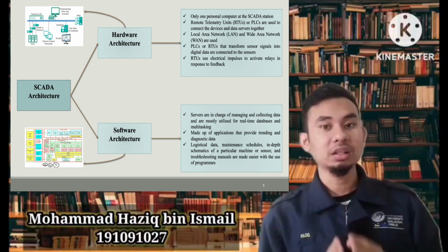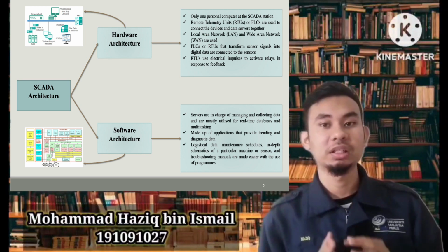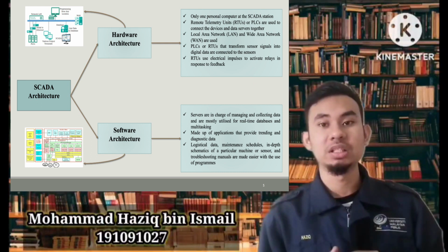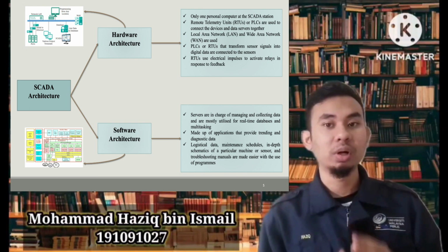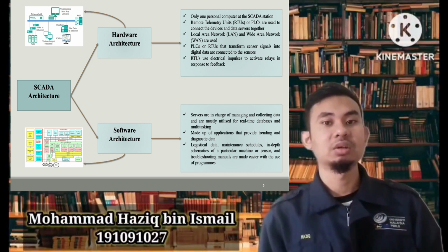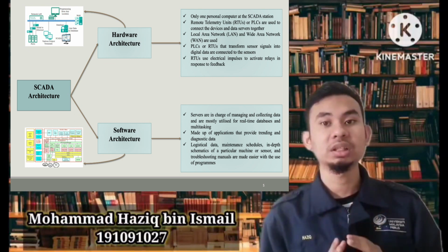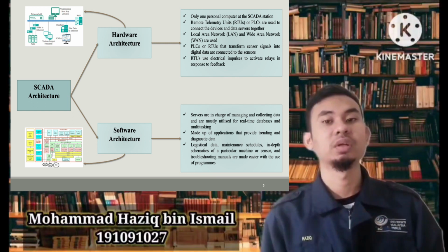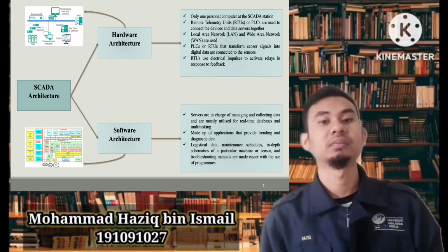Remote telemetry units, RTUs, or programmable logic controllers, PLC, are used to connect the device and the data servers together. For communication between device and the master station in the system, local area network, LAN, and also wide area network, WAN, are used. PLCs or RTUs that transform sensor signals into digital data are connected to the sensors, and RTUs use electrical impulses to activate relays in response to feedback. We can see the figure of hardware architecture at the left side in the slide.